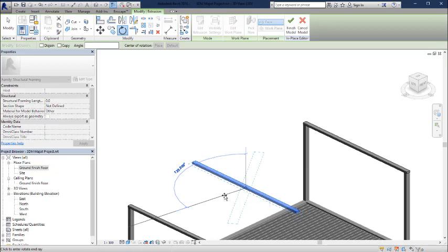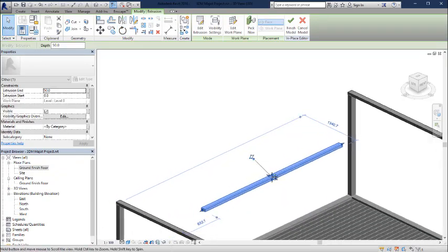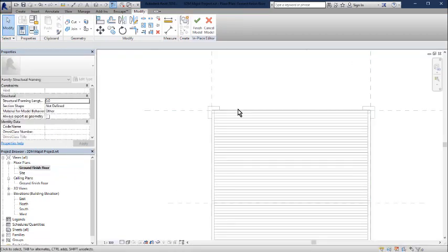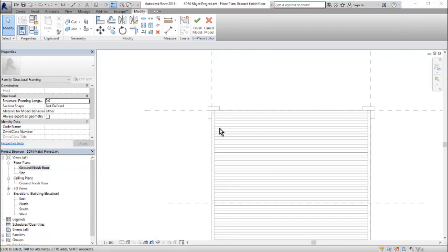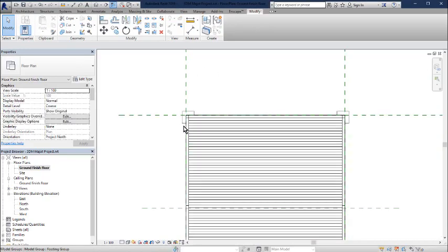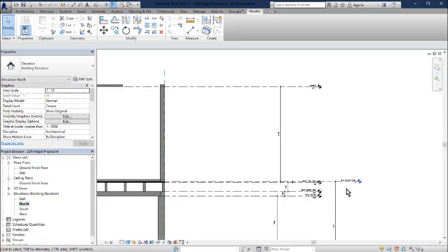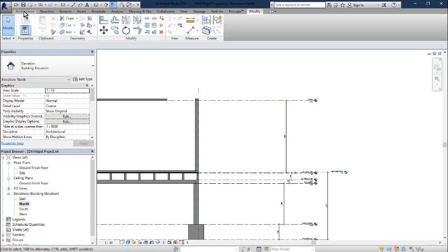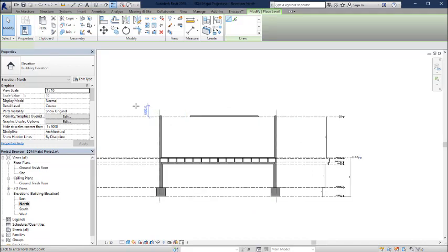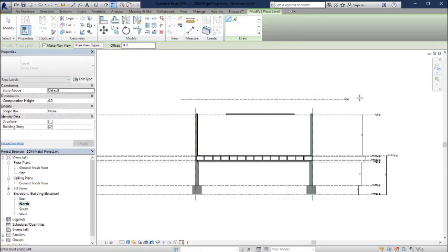So we actually need to build it first, and then we copy it. I'm going to rotate this 90 degrees, and let's go to our top view for this one now. So if you notice, when you go to the top view, you don't see that, and that's because we are actually above our cut plane. Alright, so we're gonna choose OK here, and we are gonna create another real level. That's another level like this, by going to architecture, level, and we're just going to create another level on top.